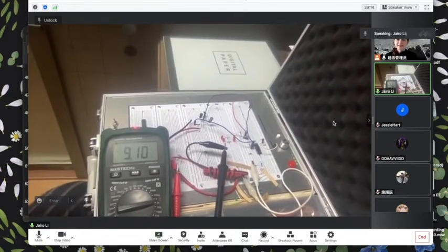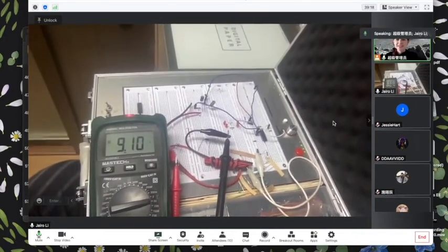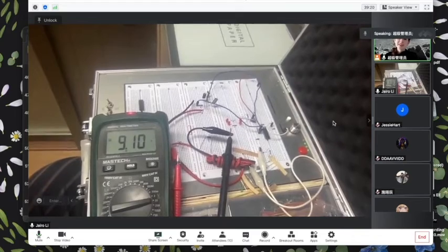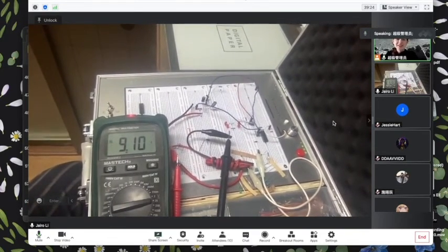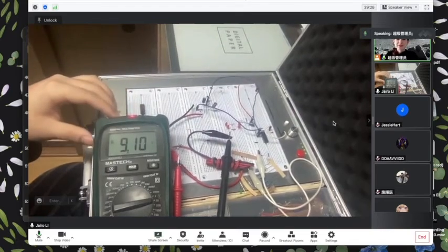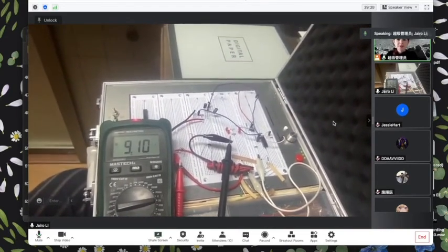It is only 9.1 volts. Yeah, that's true. There is some energy lost in each stage when you build these. That's a good demo of showing how the frequency affects it, because at low frequency, the capacitors have time to discharge more, so it's more unstable.